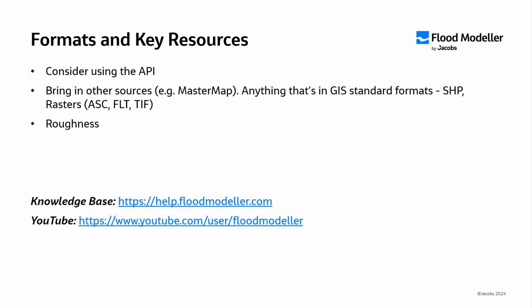If for whatever reason you have data not in one of these various formats, you might want to consider using the API to convert these data. The API is a relatively new feature in Flood Modeler, but if you have your own little Python scripts, you can draw on the Flood Modeler API to integrate its quite powerful features into your Python scripts. So if you're into that kind of automation of modeling processes, the API is for you.